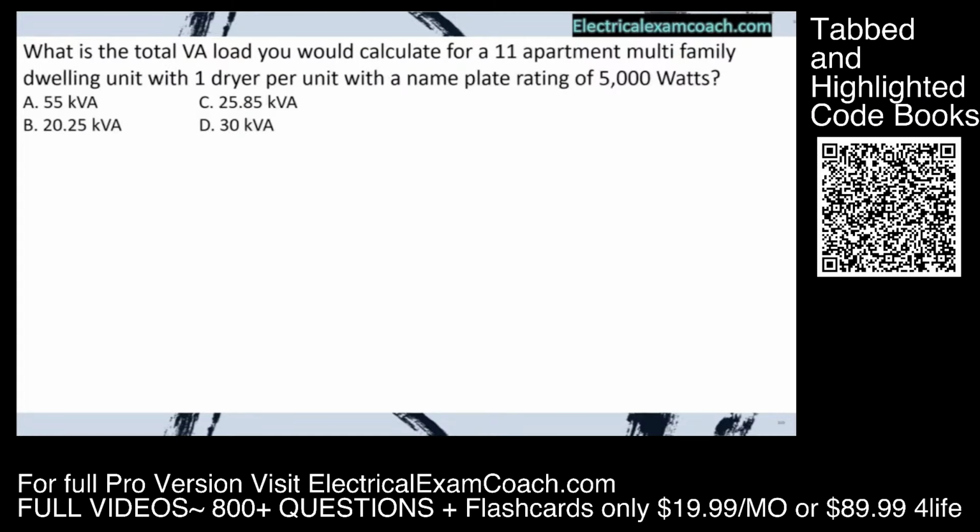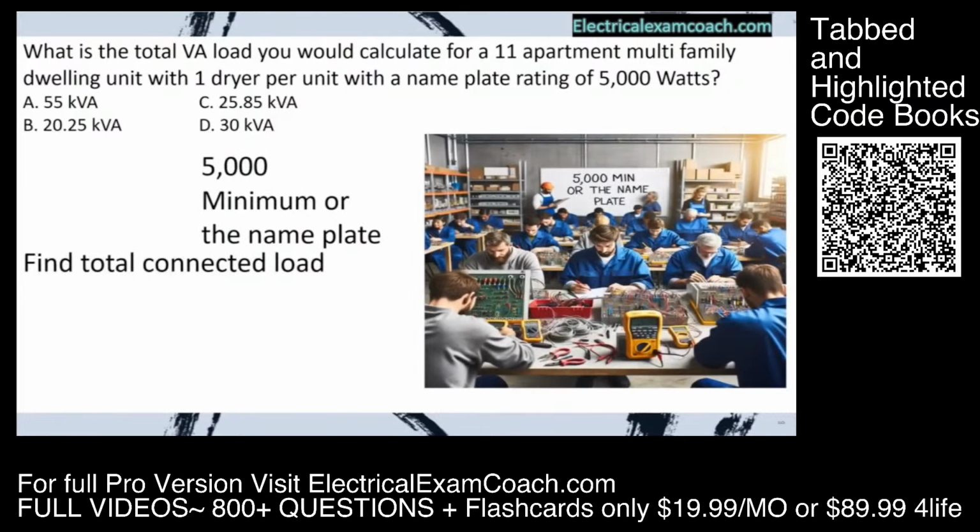What is the total VA load you would calculate for an 11 apartment multifamily dwelling unit with one dryer per unit and a nameplate rating of 5,000 watts? First, we're going to find our total connected load. We know that it's a 5,000 minimum or the nameplate, whichever is larger. We take our 11 units multiplied by 5,000, and that equals 55,000 VAs.